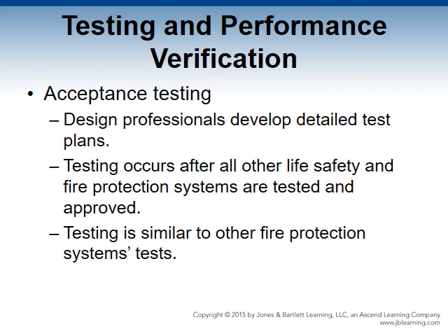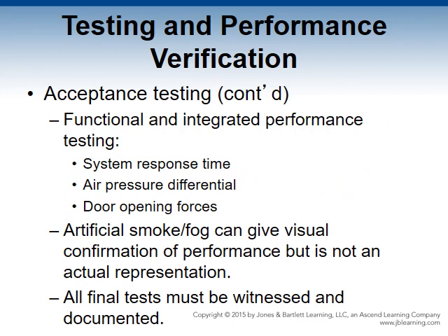It begins with an operational test at the component level. Next is the functional test of individual systems. Functional and integrated performance tests involve recording the following: system response time, air pressure differential across the smoke barrier, door opening forces in the direction of egress.